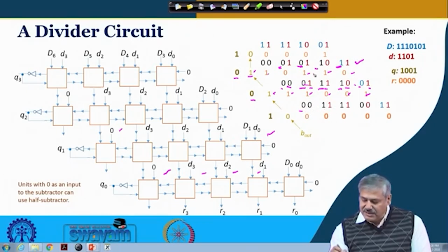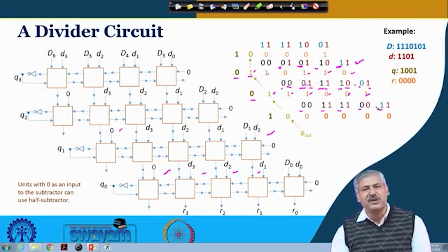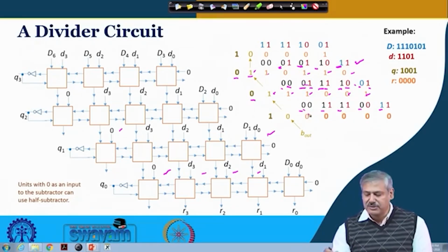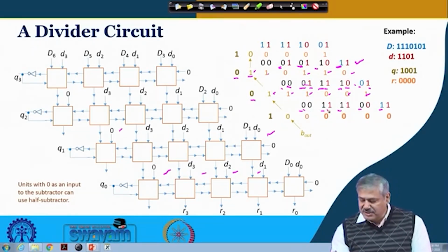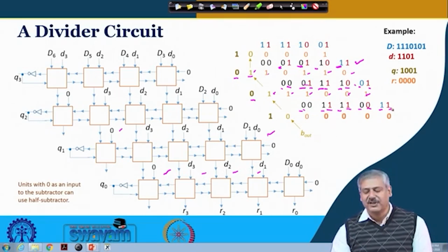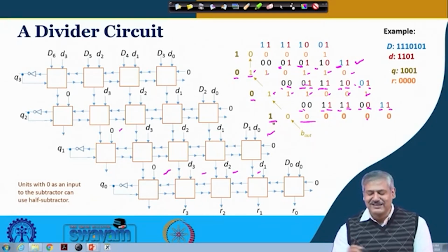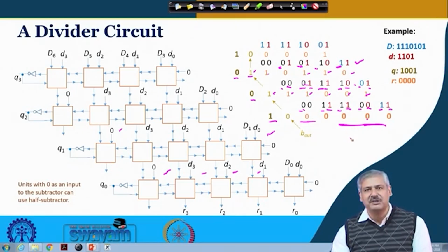0, this is 1, this is 1, this is 0, and this is 1 is coming as the D0 bit. So we have got 1 1 0 1, and over here is 0. So to be subtracted is D3 to D0. So this is 1 1 0 1. Now if you subtract, you see that this is 0 0 0, all of them are 0, and the borrow is 0. So its inverted is 1. And had there been some number present, that would have been the remainder. So remainder here is 0, all zeros, I mean R3, R2, R1 and R0.